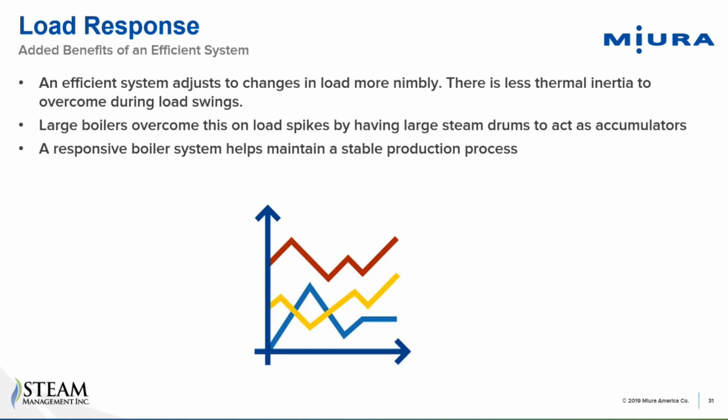Yeah, it definitely depends on how much that load is changing. But if it were perfectly constant and that third boiler never comes on, and that large boiler is not ramping up and down, probably the large boiler turned down is going to be slightly more efficient if you never have shutdowns, because the boiler is usually a little bit more efficient at that lower load. So you might have a little bit better efficiency. It's going to depend a lot on the system, though. It's hard to make a blanket statement.